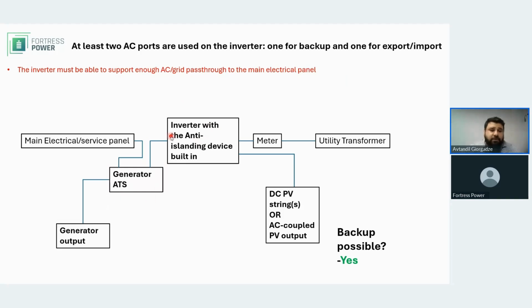For those people, there's this approach where you have the inverter, again, with all the functionality as before, except for direct generator connection. You have a separate standalone generator ATS, which you would have normally without the energy storage system if you were to only have grid and the generator as power sources. And where the grid normally would go, ATSs usually have normal, standby, and load. Normal is your grid when you have just grid and the generator. Standby is your generator, and load is load. Doesn't matter whether it's in this configuration or a generator plus grid only configuration.